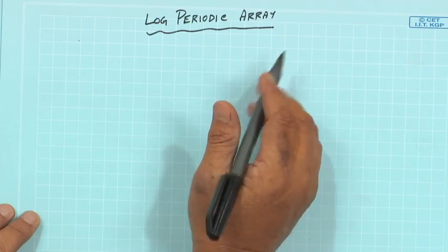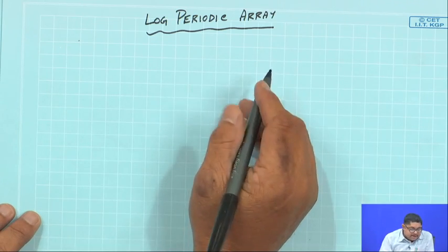But the problem is that this type of broadband antenna, where I can send several narrowband signals, is dispersive in nature. If I send a pulse, it needs all the frequencies to be passed simultaneously. That cannot be done by this log periodic array. So, it is a dispersive array, that means there is dispersion if I try to send a pulse, but if I send narrowband signals, then over a very large bandwidth it can pass those signals. In that sense these arrays are called broadband antennas.